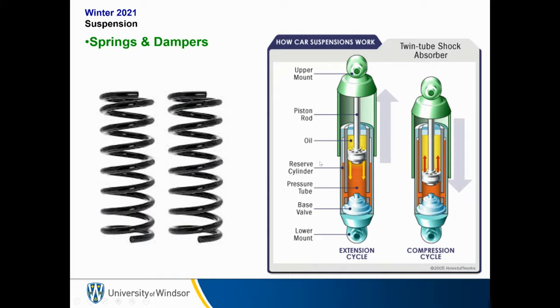So this is what's used in, I believe, the Camaro, the Corvette, and what was the Cadillac CTS-V, I believe now the CT5-V. They use what are called magnetorheological dampers. Basically, you can control the damping rate based on the electric current being run through the ferrofluid. It's pretty cool technology, and one that GM is actually ahead in the world in terms of utilizing, which is surprising because GM doesn't really make good quality products anymore.